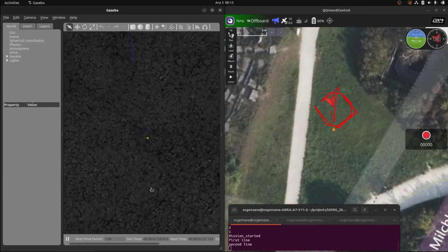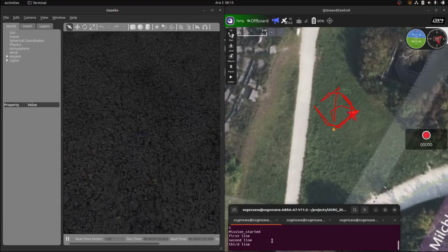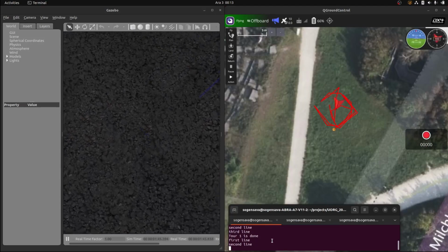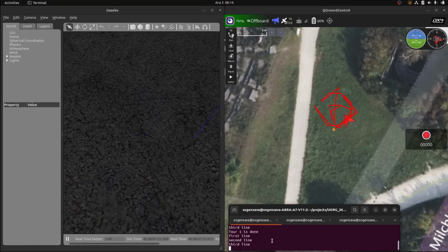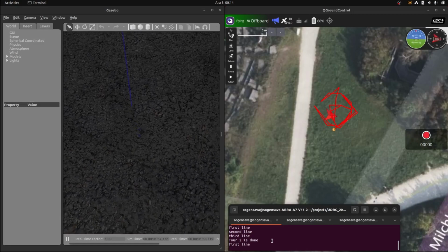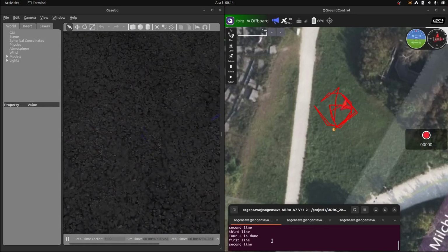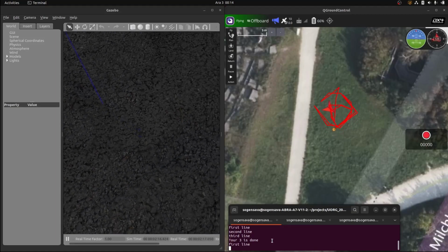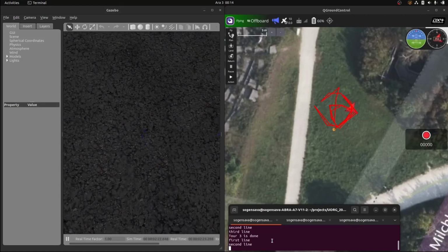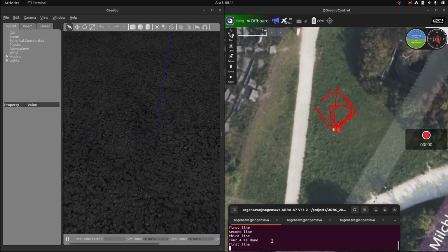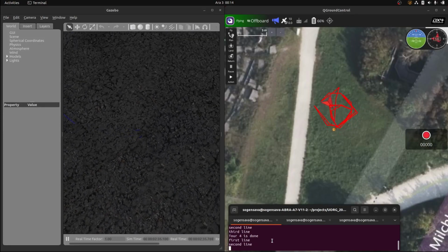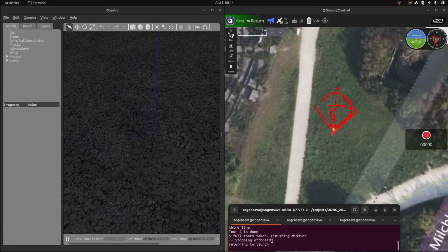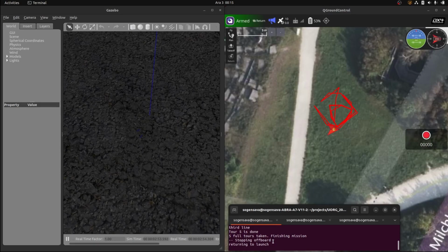For simulation and real-time execution environments, we used the PX4 environment because it was necessary for computation. It was a great open-source autopilot software. Our code is written in a way that with slight modification, different environments could be used, such as ArduPilot, AirSim, etc. Python is used as the programming language with async programming, and the MAVSDK Python library is used for controlling drone movement and gathering information from the drone. As ground control station and 2D visualization tool, QGroundControl is used, while for 3D visualization, Gazebo is used.